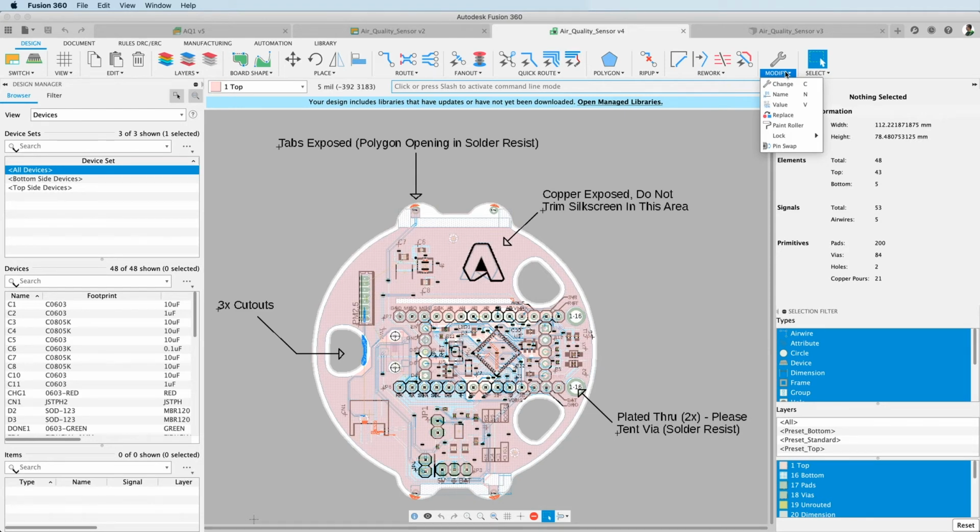A few more words on this bar on the bottom here. There I have the zoom in and zoom out options, the grid command again, and very important, this one here, please click on it. It's interesting, if you move components, if you route signals, you can decide about the mode. By default, it's set to push violators. This means as soon as I move something, obstacles would be pushed away.